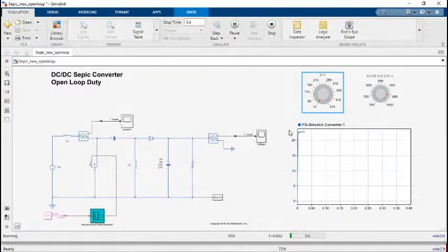And so you see that we are getting constant voltage here. There is no change in this voltage, right? Somewhere around 25 we are getting here. So this is boosting right now because of this controller. It is boosting because we are giving 12 volt, and we are getting around 20 to 25 volt, right? Okay, so it is still running.